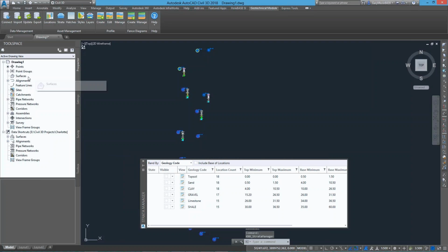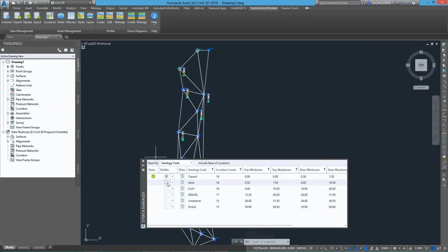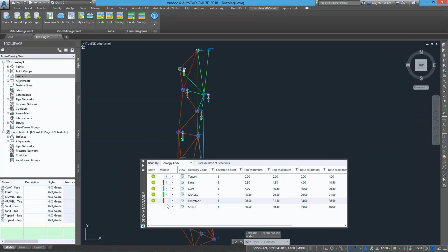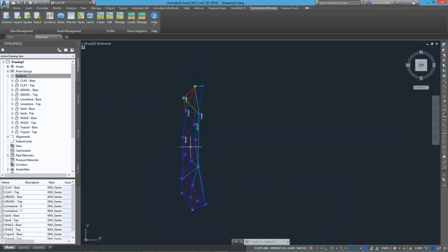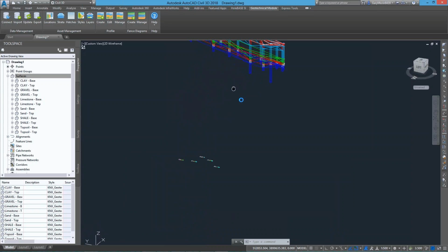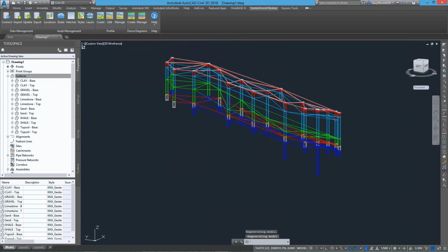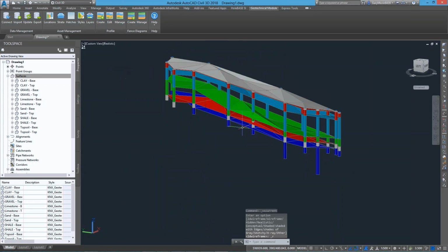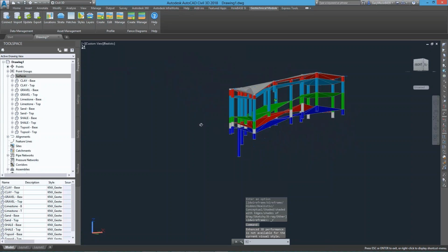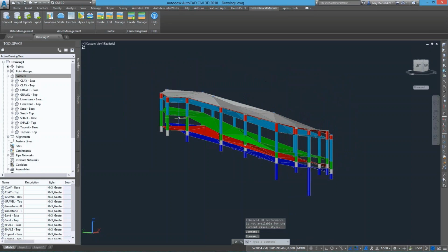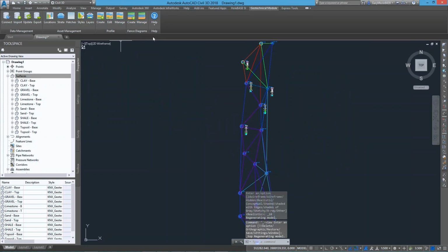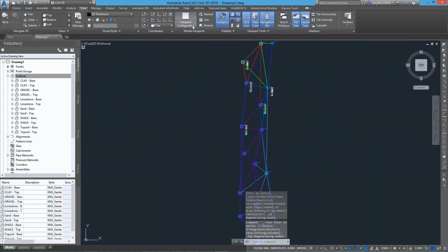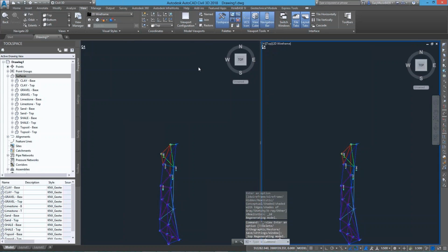I've now just gone into one of the really interesting areas of the geotechnical module, the strata manager. We've got a drawing here with no surfaces in, but in those few seconds we've just created 12 AutoCAD Civil surfaces based on the geology, top and base surfaces for each geology material, and there we have it. Now I must emphasize, this is just the starting point of modeling your geology. I've got some pretty nice clean data here. In reality, it doesn't come in that clean. You need to check, model, validate your information, verify it, and use AutoCAD Civil commands to help model it.